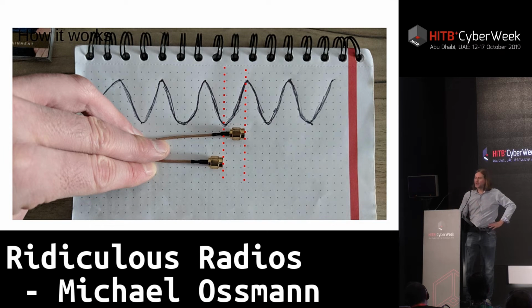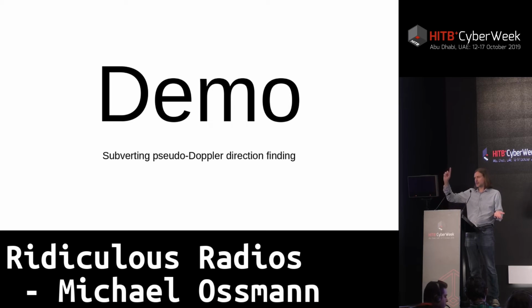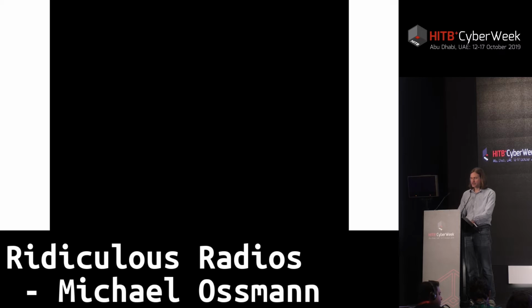And what we did was we connected two of these cables using the Opera Cake as the switchable delay line between the Bluetooth dongle that was creating the signal and the actual transmit antenna. So we have these two different delay lines, and we switch back and forth between them. And he wrote this little program to just switch back and forth between them in a pseudo-random way, trying to fool my direction finder.